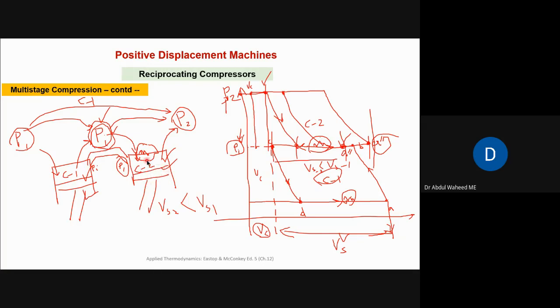अगर इसका volume बड़ा होगा तो it means कि यहाँ पे further expansion हो रही होगी. So that volume should be less than this volume, right? So that उसका pressure drop ना करे, उसे PI पे रहे when it is entering into the second stage compressor. If its swept volume is more than the swept volume of this one, this pressure may drop because volume is increasing.